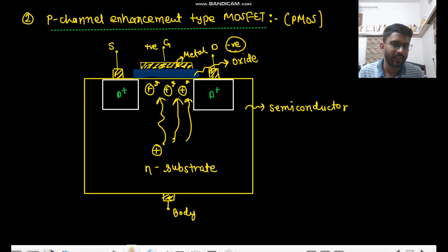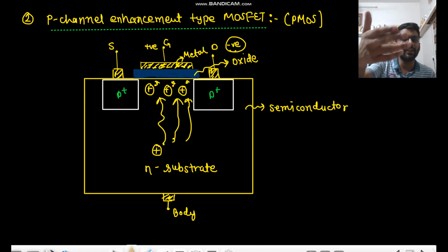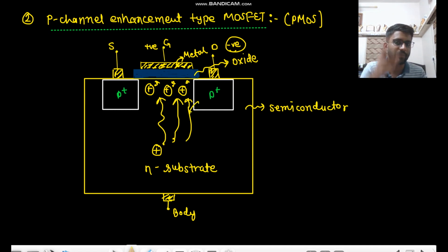Like there is depletion layer as well. In the depletion layer, the electrons will feel the force and go towards the drain. But the drain will not accept them, because the drain is negative. And if you apply positive at drain, then the depletion layer will not be formed here, and strong electric field will not be there, and then the electrons would not be swept away. So both conditions are not getting met, right?